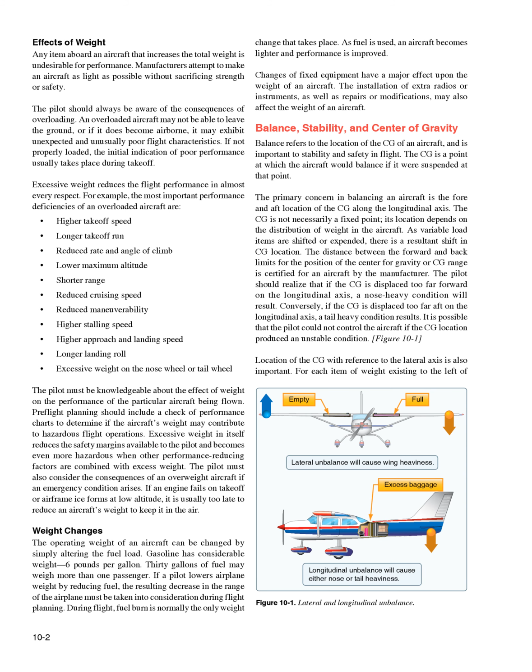Effects of weight. Any item aboard an aircraft that increases the total weight is undesirable for performance. Manufacturers attempt to make an aircraft as light as possible without sacrificing strength or safety. The pilot should always be aware of the consequences of overloading. An overloaded aircraft may not be able to leave the ground, or if it does become airborne, it may exhibit unexpected and unusually poor flight characteristics.